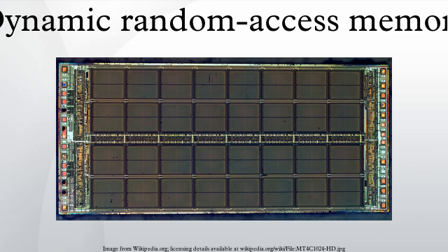Synchronous graphics RAM. SGRAM is a specialized form of SDRAM for graphics adapters. It adds functions such as bit masking and block write. Unlike VRAM and WRAM, SGRAM is single-ported. However, it can open two memory pages at once, which simulates the dual-port nature of other video RAM technologies.